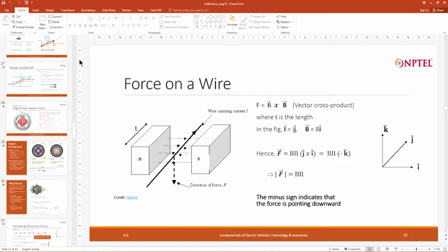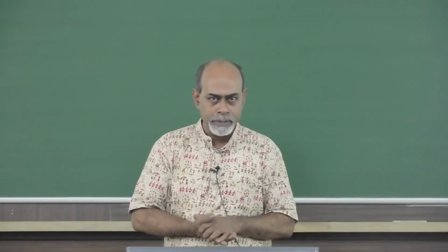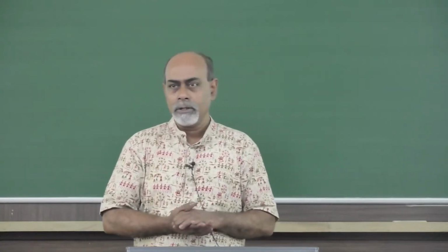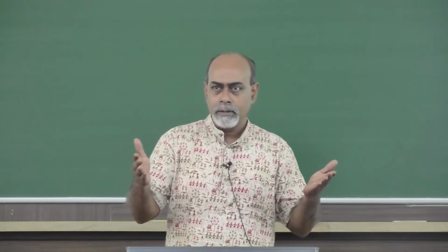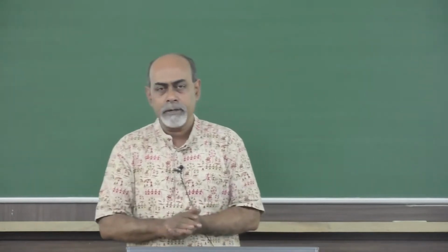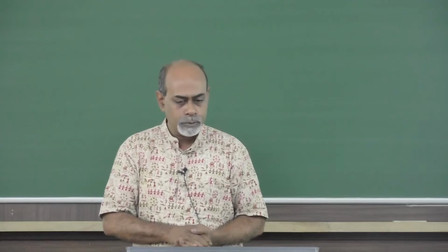finally, we looked at what is called magnetic torque and what is called reluctance torque. Reluctance torque is something that we get along the way, it is not intentionally driven. By far the most prominent torque with a permanent magnet motor is the magnetic torque, but in addition, the fact that there is steel in the form of the rotor core along the way of the magnetic field means that it will tend to be turned in some direction, and that is what contributes to reluctance torque.